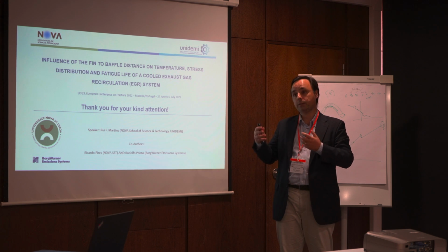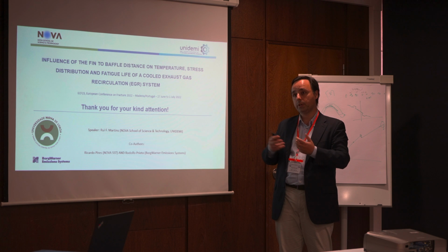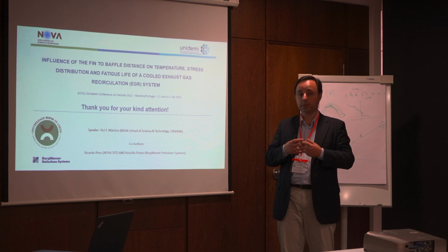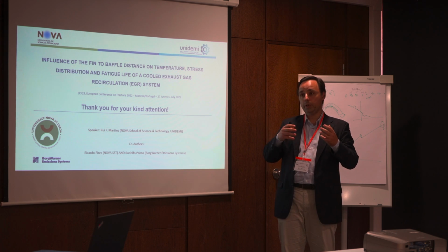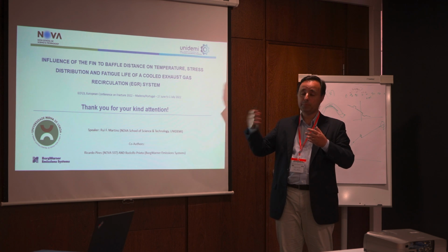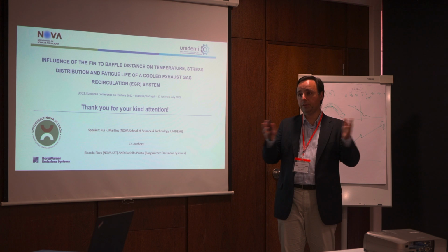They are not applied strictly to those temperatures, but they make sense just for a first estimate of the fatigue lives that can be expected in this type of equipment. By doing this, we estimate some fatigue lives that we compare with the design requirements, and then we define a fin length.